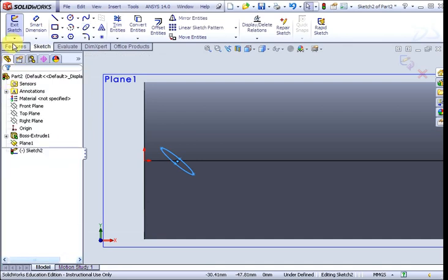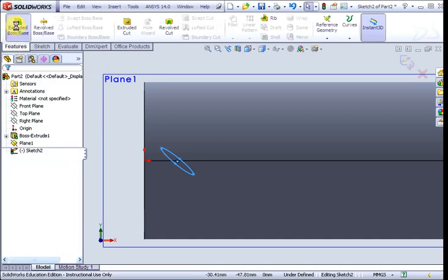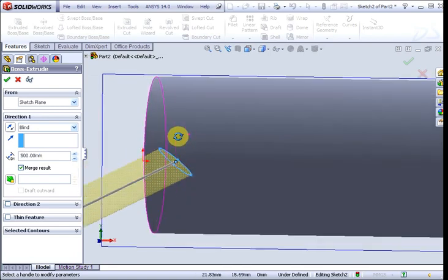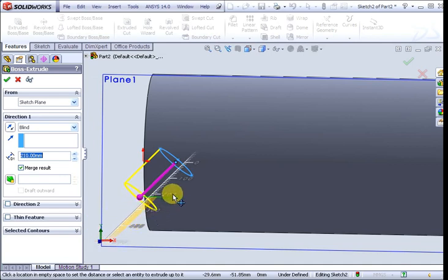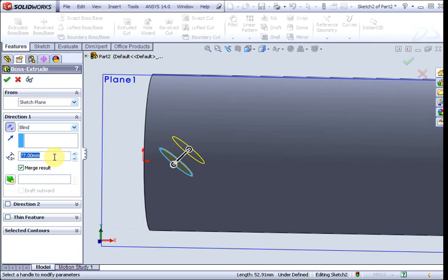Okay, it is ready. Now we can do the extrude for the blade. This is one blade or vane of the swirler. This is obviously the wrong direction, so we have to reverse it. The diameter is about 100, so we have the radius 50, but this is a bit off center, a bit out, so the plane is 5 mm outside, so we will do here 50. That will leave a distance from the center about 5 mm.